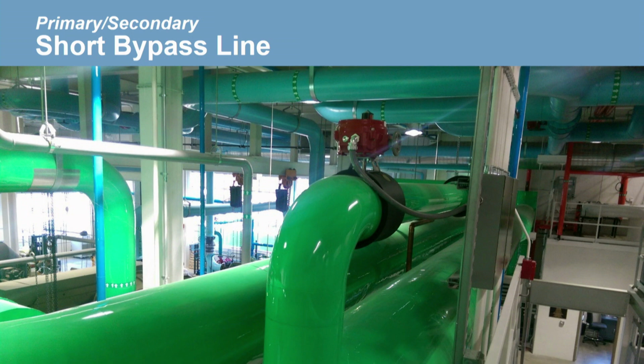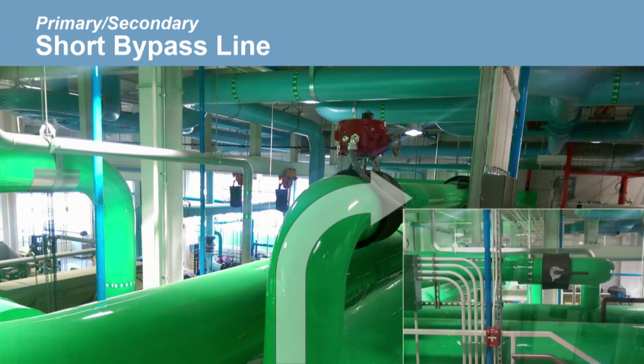Consider what was done at this chilled water plant, where they came out of the supply manifold with a properly sized pipe, used an elbow, then ran the pipe along that manifold to 2 more elbows to connect with the return manifold. That adds a small pressure drop to keep water from short-circuiting through the bypass. So that's for primary-secondary systems.